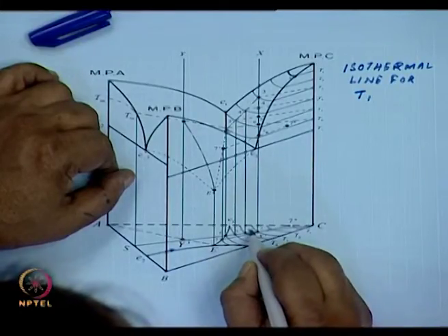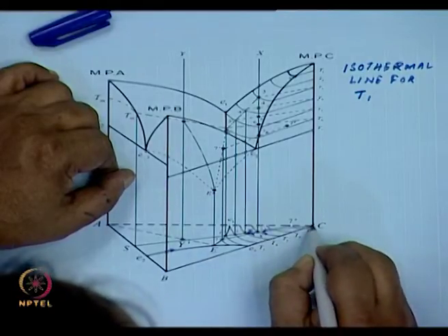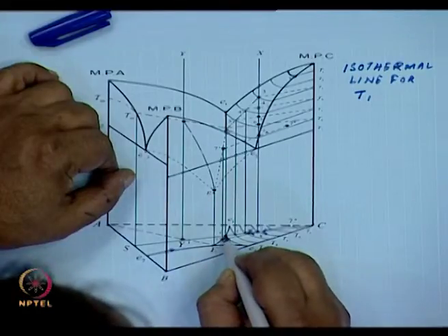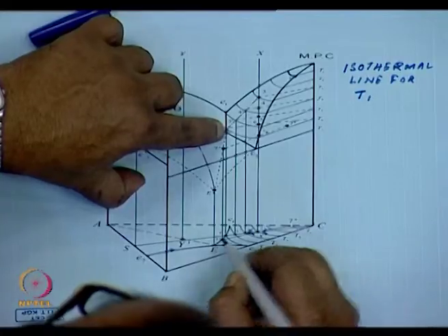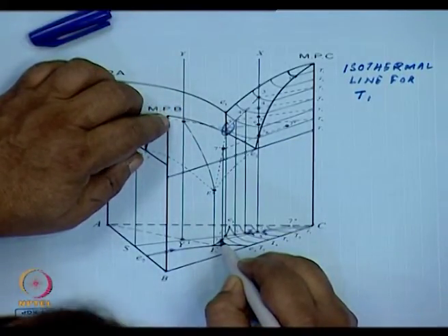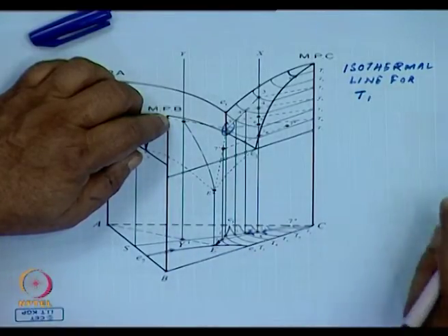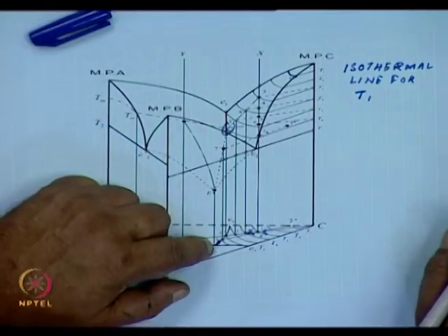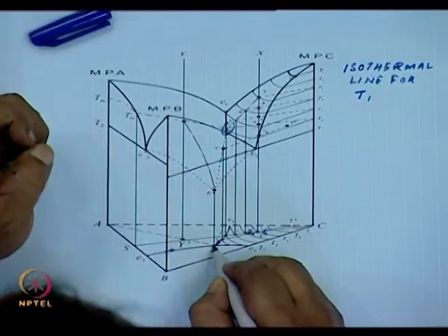So far it has occurred on the two-dimensional plane on this way, that is the join of C with all these temperatures. As it has reached 6, which is at the eutectic line over here, what happens? It encounters the E1 eutectic line, and then the cooling starts in this particular path, so that all materials freeze at this particular point, which is the E.